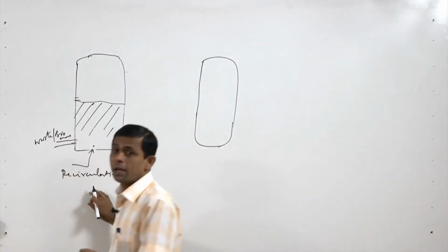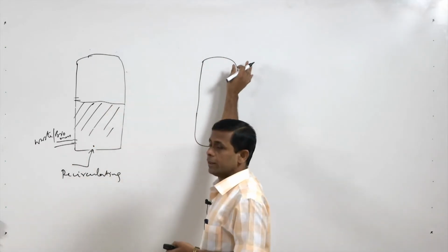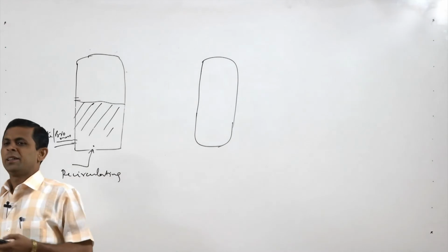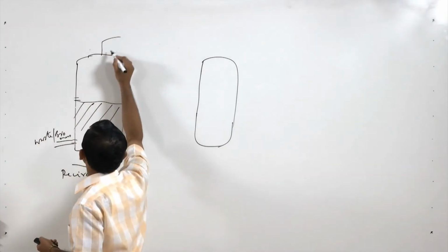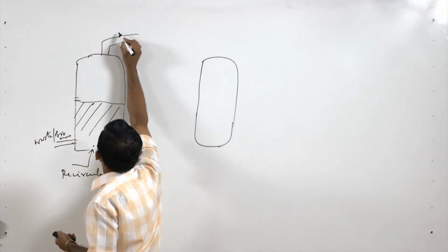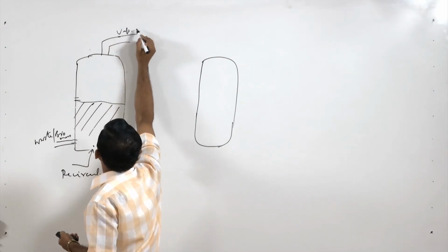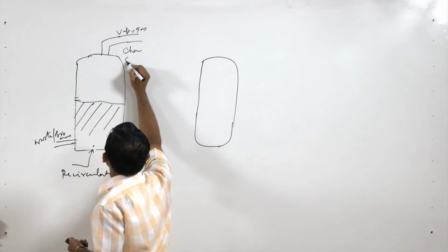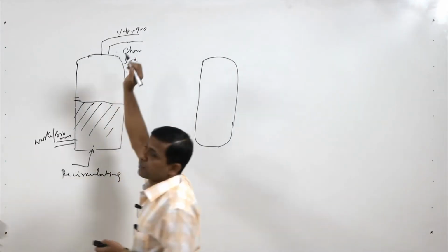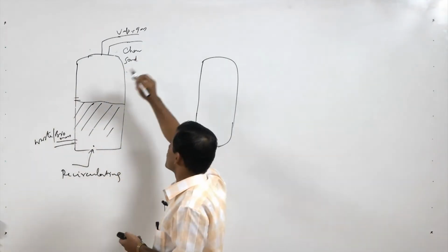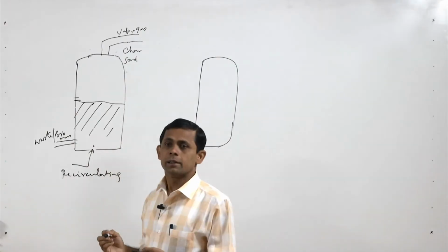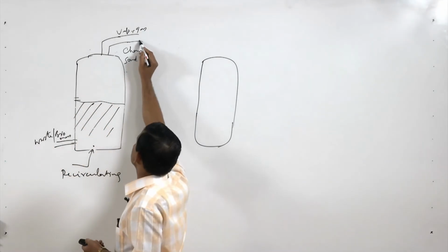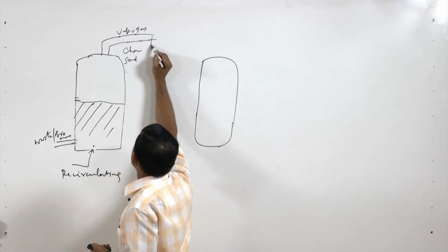Recirculating gas, where does it come from? It comes from the second chamber. Here the pyrolysis takes place. Pyrochar along with vapor, gas, char and sand all come from the top of this pyrolyzer, because high velocity is maintained here. So it comes out, and then it is separated.